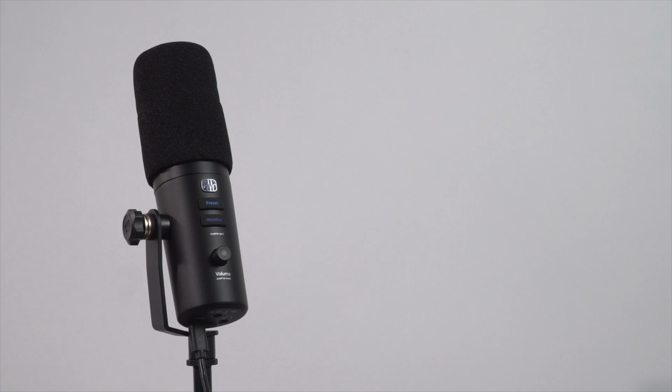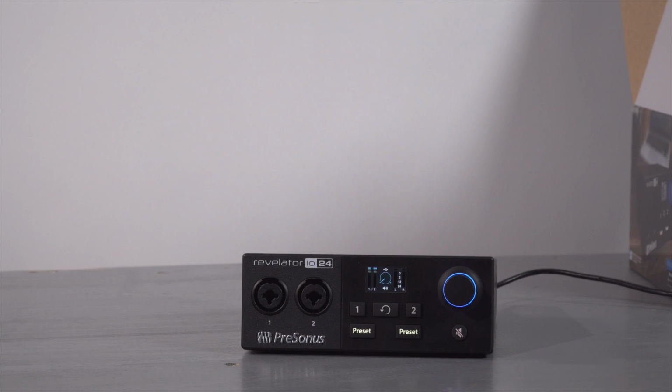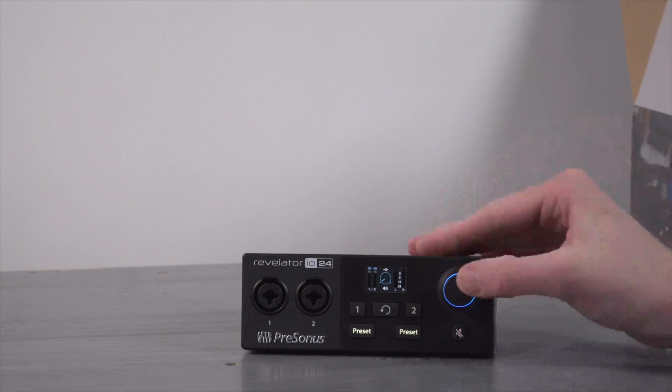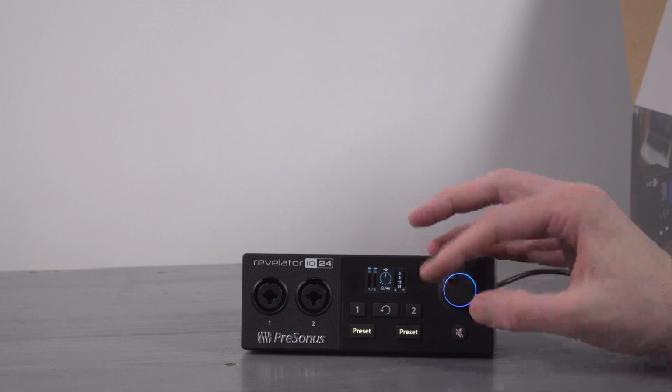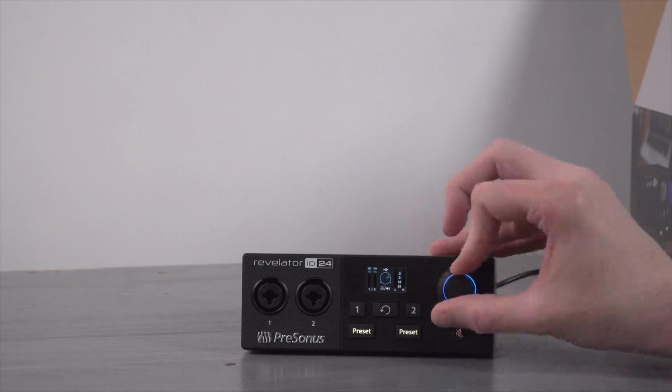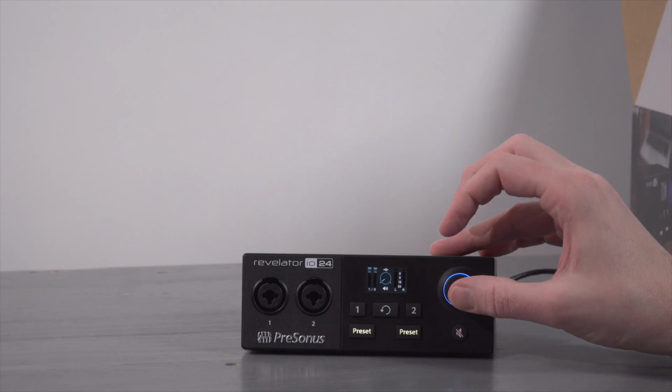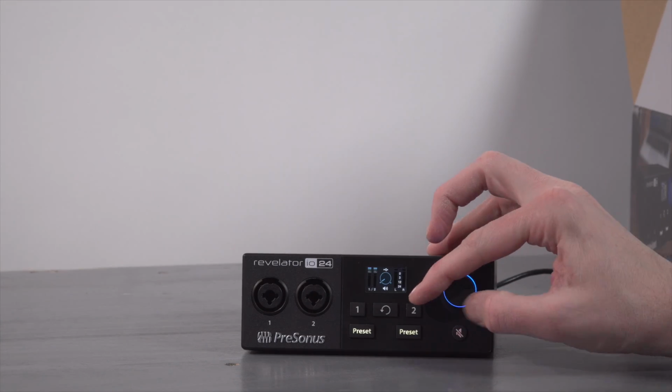All right, so this is the Revelator Dynamic on the Broadcast Lite preset that I've been using so far in this video with 40 dB of gain, so this should sound pretty similar to how I sounded before. With the RE320, we needed about 10 dB more gain to get the same level into Reaper to record. So we're at 50 dB of gain on this microphone, the fat channel set to broadcast with the gate turned off.